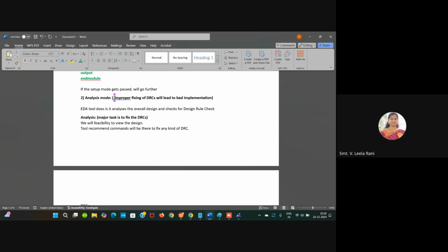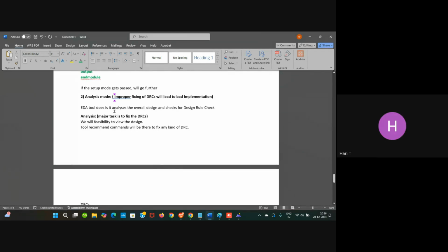During that process, we designed the layout also, when company people came to give us training. So during the layout designs, we saw the DRC checks. Okay, DRCs will be a part of physical verification as well, because PD will also face this terminology. The PV person will do geometrical checks and compare LVS, layout versus schematic. Yes, sir, we have used LVS.